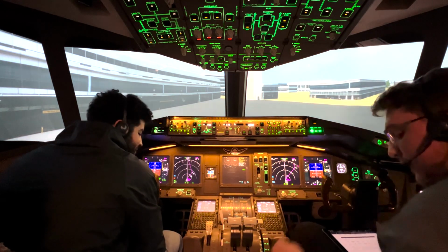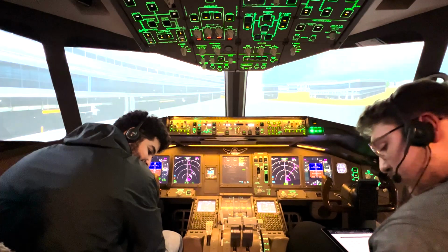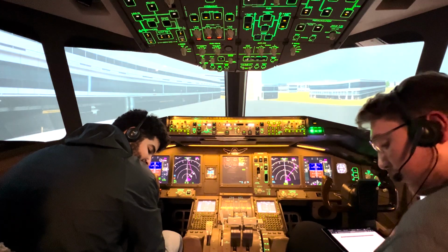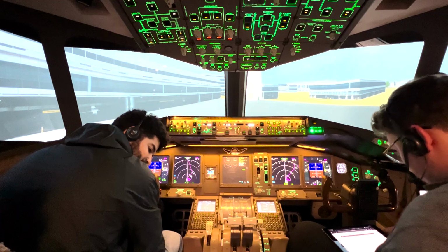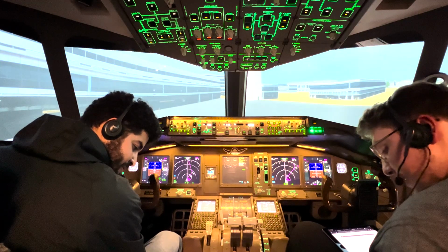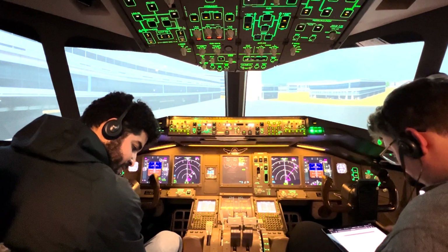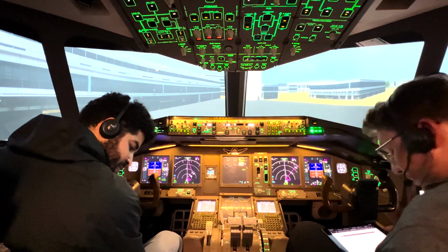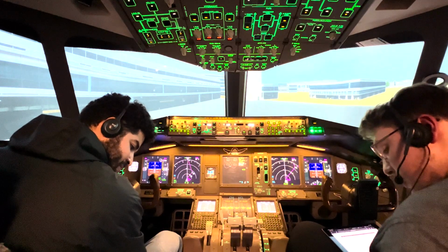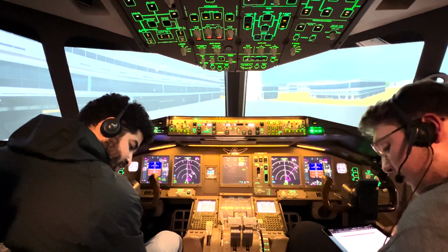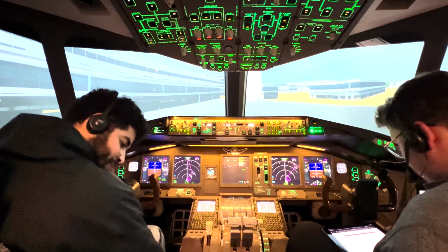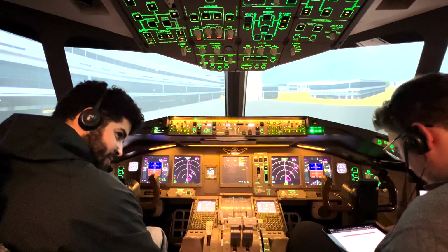We'll go ahead and load up our fuel and passengers. So we'll go to menu, sim options, sim, load payload, and our payload for today is a zero fuel weight of 187,958 kilograms. Perfect. And our fuel load for today is going to be 30.47. That's our total fuel. So we have no fuel in the center tanks, and we'll have fuel in the wing tanks, left and right tanks only. Okay, so that's our flight plan, payload, and fuel.